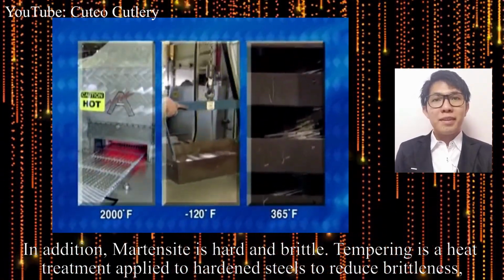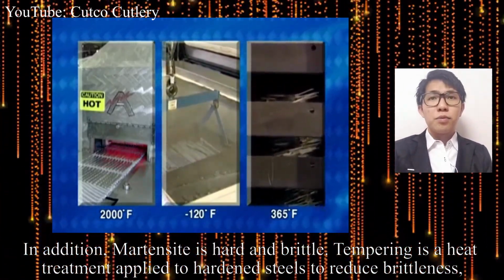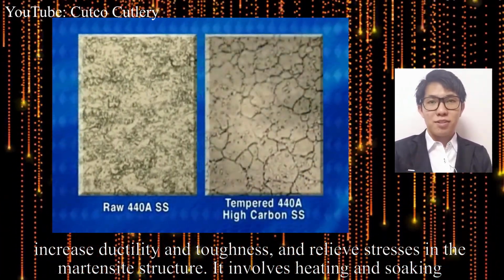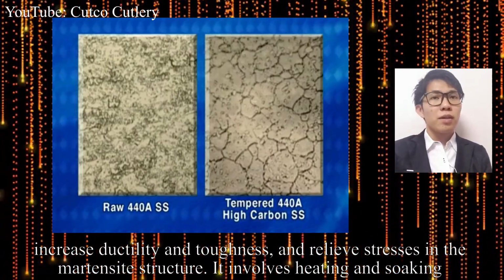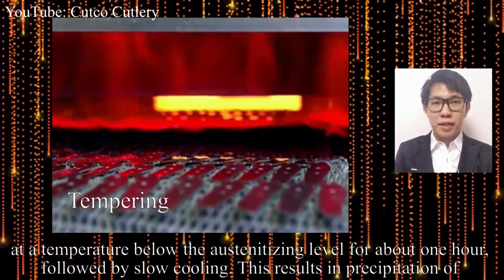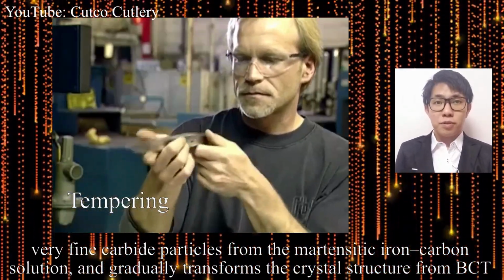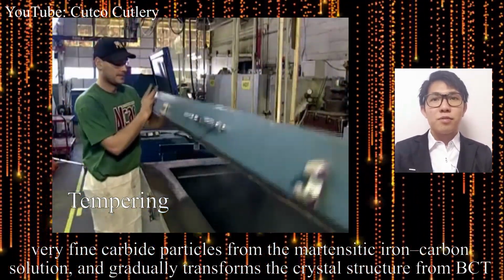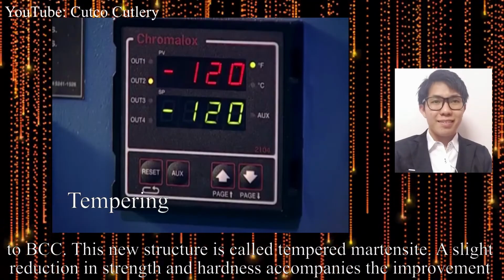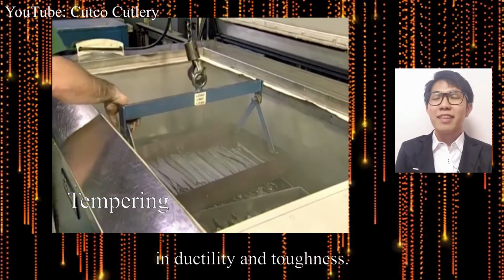In addition, martensite is hard and brittle. Tempering is a heat treatment applied to hardened steel to reduce brittleness, increase ductility and toughness, and relieve stresses in the martensite structure. It involves heating and soaking at a temperature below the austenitizing level for about 1 hour, followed by slow cooling. This results in precipitation of very fine carbide particles from the martensite iron-carbon solution and gradually transforms the crystal structure from BCT to BCC. This new structure is called tempered martensite. A slight reduction in strength and hardness accompanies the improvement in ductility and toughness.